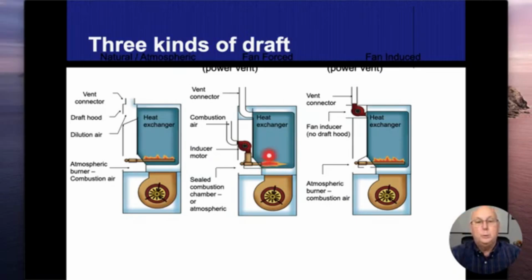The reason we don't do this anymore is that when the furnace is starting up and I have a fire going inside, if the inside is pressurized and there's a hole anywhere, I'm going to end up pushing those combustion gases, the after-fire gases, or the carbon monoxide into my circulation air. Depending on how big that opening is and where it is, that may happen after the blower fan kicks on. It will most likely happen before the blower fan kicks on.